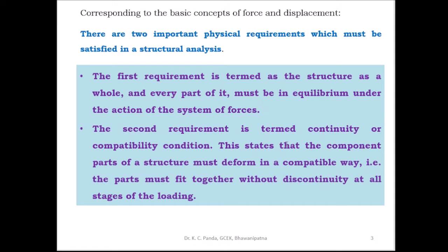The first requirement is termed equilibrium: the structure as a whole, and every part of it, must be in equilibrium under the action of the system of forces. The second requirement is termed continuity or compatibility conditions. The component parts of a structure must deform in a compatible way, that is, the parts must fit together without discontinuity at all stages of the loading.